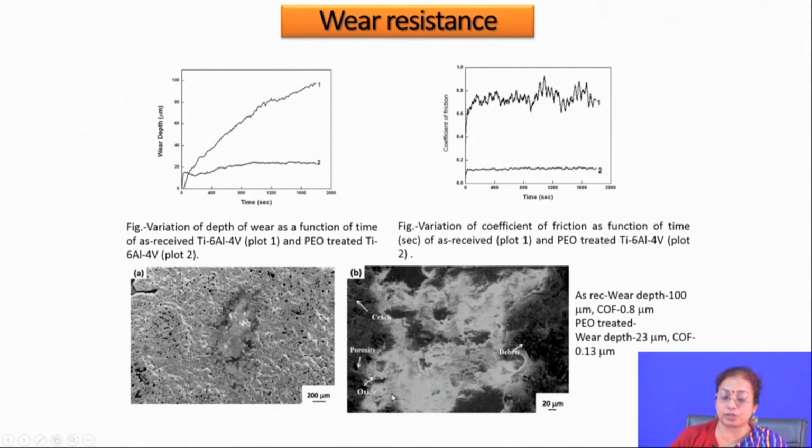So you will find a lot of charging effect from the surface. And when you do wearing further, that oxide acts as an interlayer, and as a result the coefficient of friction decreases, because the wear changes from two body to three body wear.